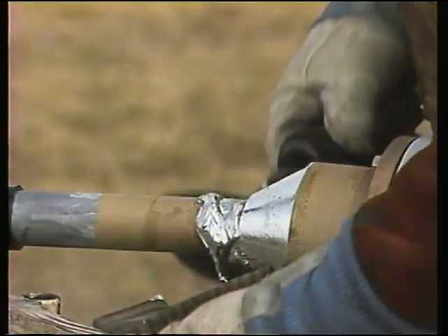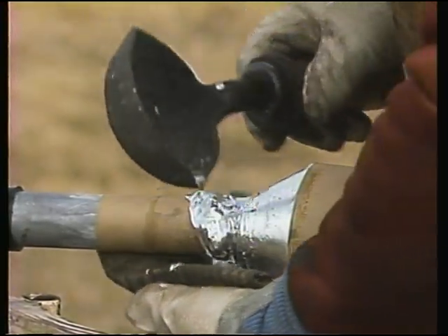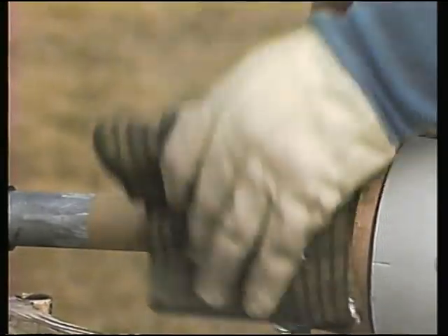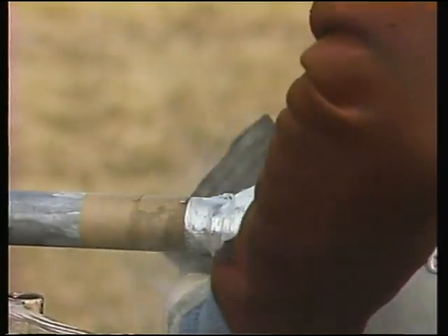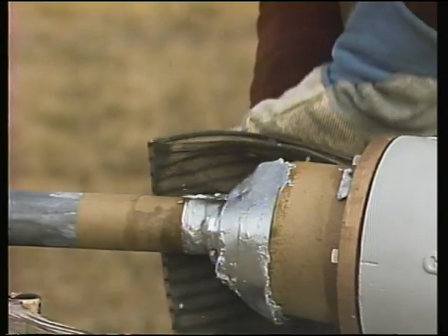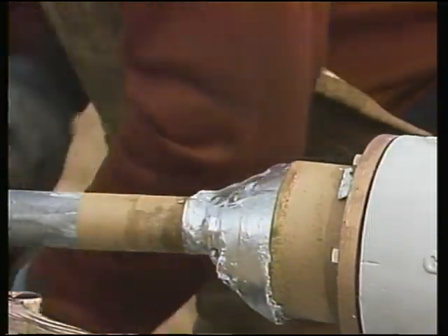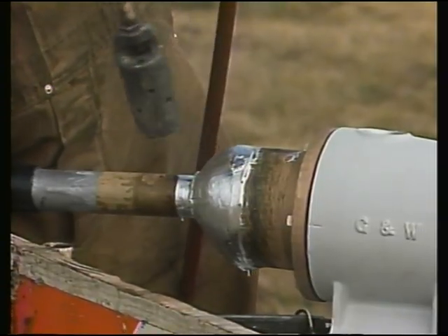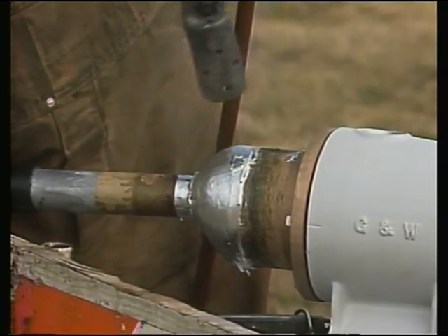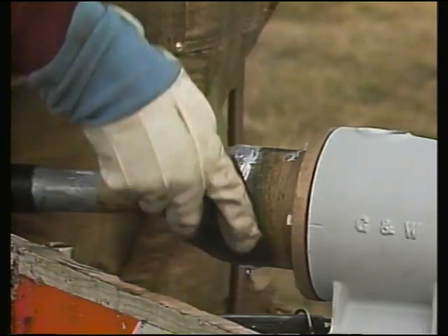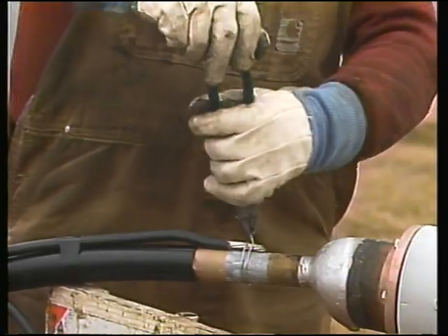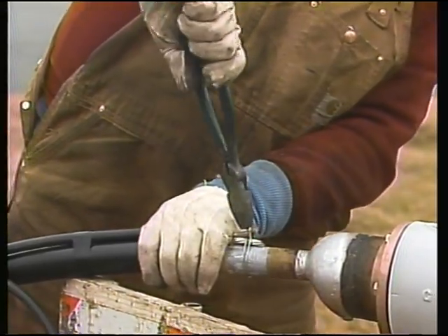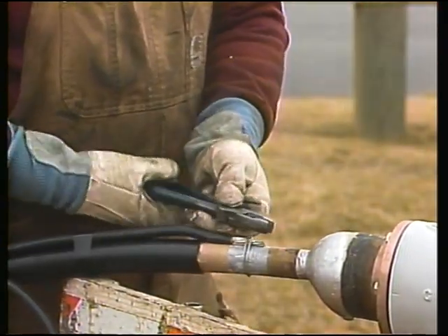Then the melted solder is poured around the metal base, and a fire-retardant cloth called a wiping cloth is used to wipe the solder around the sleeve. A solid metal seal is formed as the solder adheres to the tinned metal terminator base. To smooth out the solder, the workman uses a torch to reheat the sleeve, and he wipes the solder again. After the seal is complete, he attaches a ground wire to the lead cover and solders it in place.